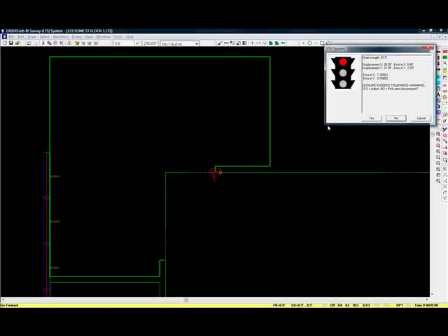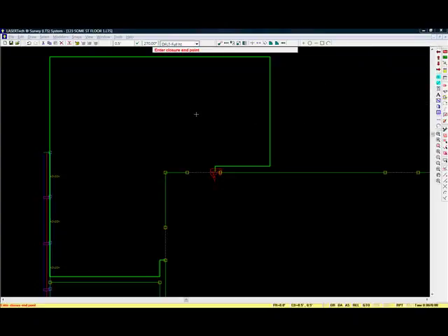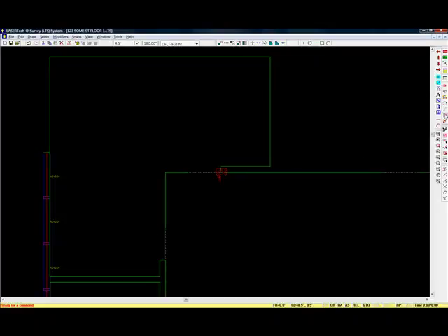Now it's saying we're out 0.45 in X. So obviously I've got something wrong because I'm out too much here. My error in Y is acceptable, so I would have to go back and find the error. So the surveyor would look and he could see that it's either in here or in here. So let's say he clicks on here and he discovers that's not 5 feet. He measures it again and it's 4.5. He must have messed up on his laser shot. So he accepts that, and now he does a closure check again, and now he gets the green light and adjusts.